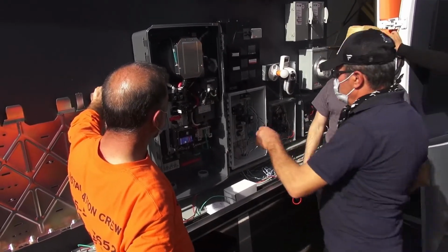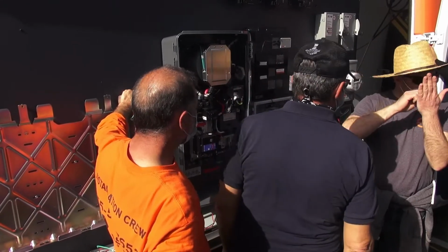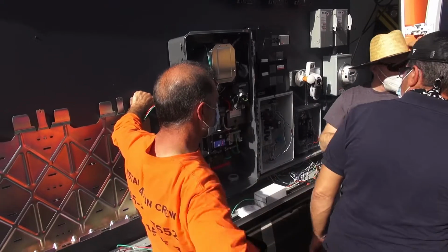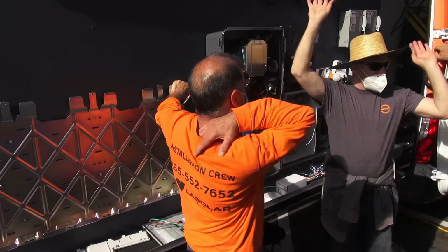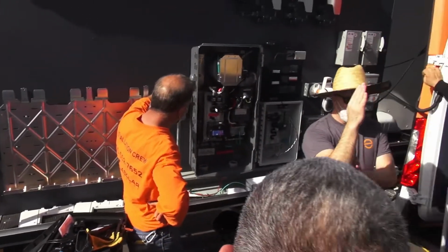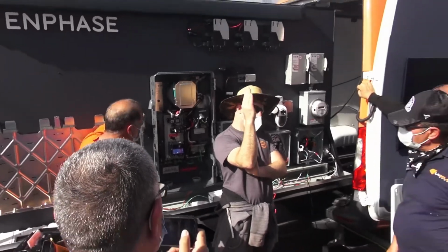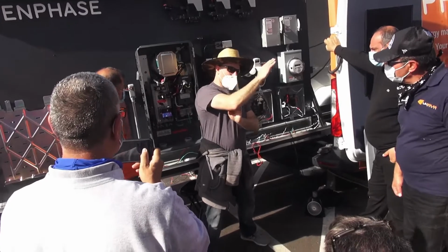Help me out. Click it to the right for me. Okay, now you'll power it on. It'll go through its little safety checklist. Takes about 45 seconds, and then it will move the switch around. Everything will come to life. The grid goes out, your stuff stays on. But do you get that point? So which way should the switch be before you turn it on? This way or this way? To the right.